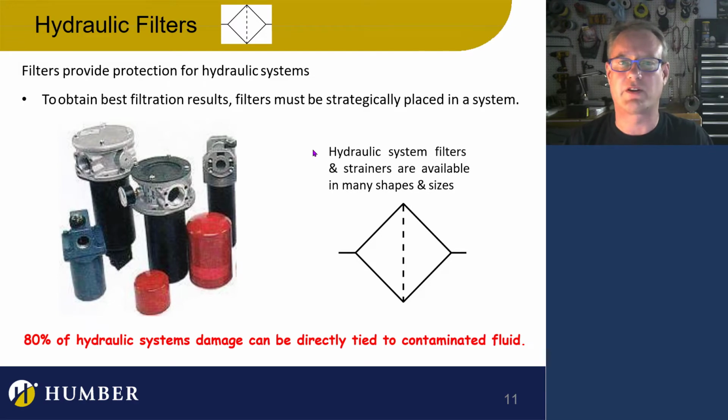So let's talk about filters. Now, filtration is really huge, really big. The reason filtration is so very important, filtration is probably the most important part of a hydraulic system, period. And the reason is because 80% of hydraulic system damage can be directly tied to contamination.